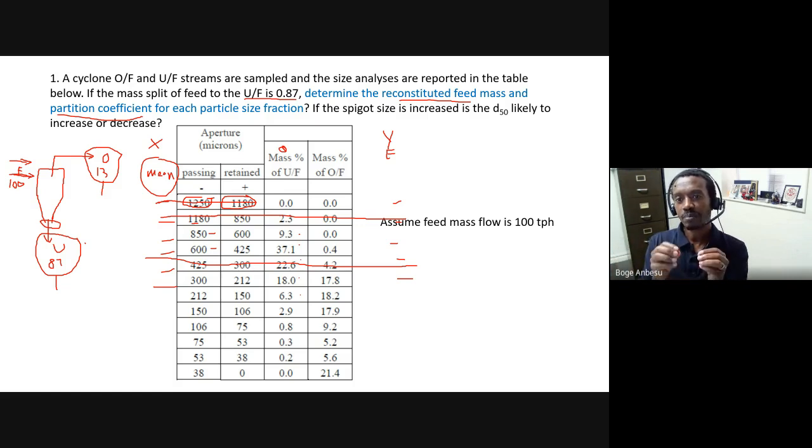Water quality becomes a problem only when I have coarse particles in the water but what I'm trying to separate is even finer. Otherwise, TDS alone shouldn't be problematic, especially if what we're separating is coarse particles in the millimeter range. Then I wouldn't even worry about water quality.